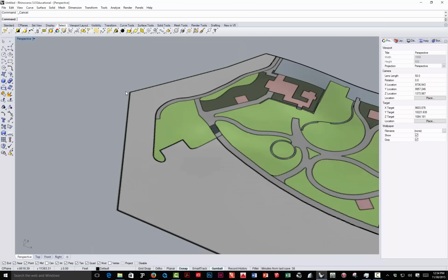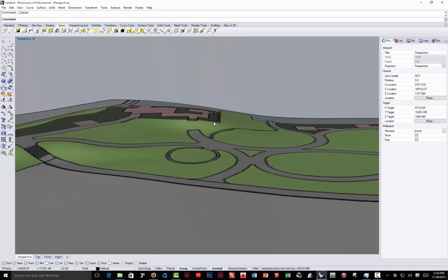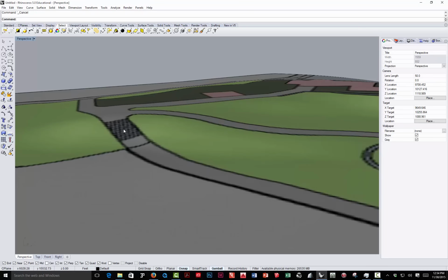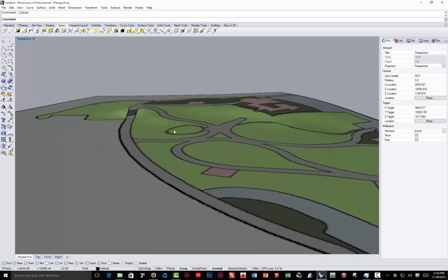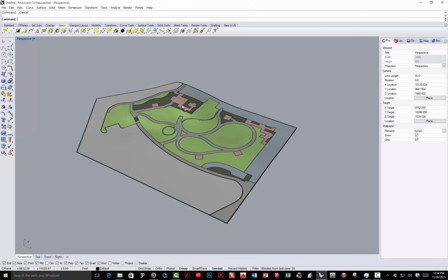There's the edge, right out there at the edge, and you can see now that the terrain surface here, where the wall is going to go, where the stairs are, needs to be adjusted, and this little seating area is still sloping down a little bit. Those are the 3 areas I'm going to adjust first. I'll start with a new command that allows us to adjust these 2 areas, the circle and this, really quickly. Then we're going to drop the walls and a set of steps in here and show you how we can add some other control points to help us adjust those pretty quickly as well. And once we've got all the terrain adjusted, we go through the split process in order to apply different textures or materials to different surfaces.